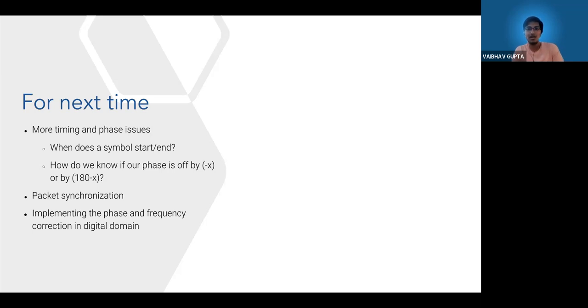We talked about how there's some timing offset that might cause an error with the carrier frequency, but that carries over to the symbol as well, right? When we were talking about a symbol starting and ending at a certain point, we assume that the two ends are sampling at the same points. If they no longer are, it becomes a bit harder to say where one symbol starts and where the next symbol starts.